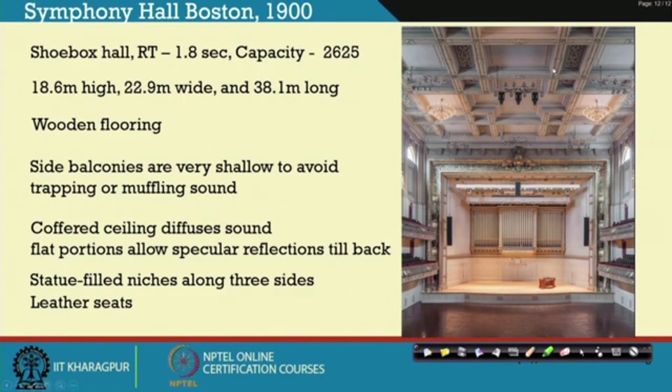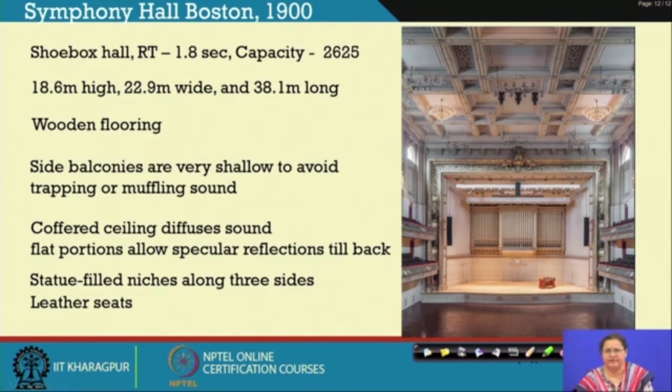22.9 meters, that is around 23 meters, and obviously the single beams would have been very heavy. So, these coffered beams were planned, in which the edges of the beam allowed in diffusing sound, and the flat slab areas actually helped in reflecting sound. So, these particular segmented areas helped in reflecting sound into the audience, and these projected soft beams all helped in diffusing sound into the hall.